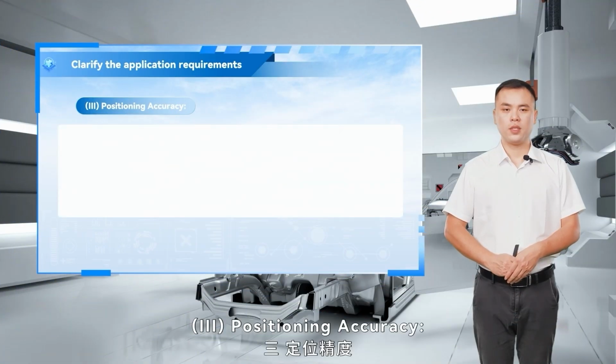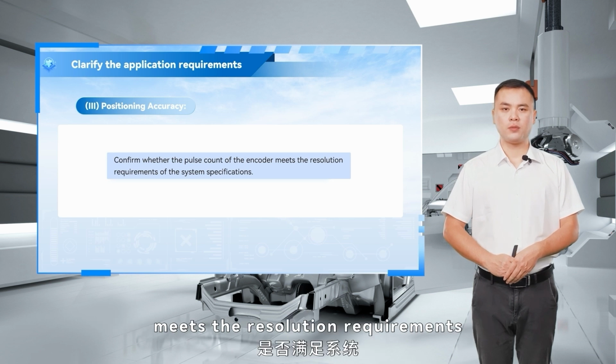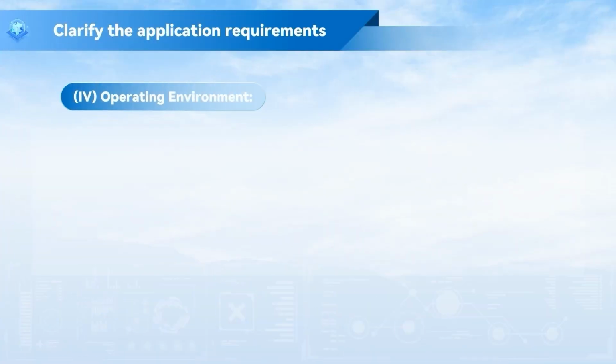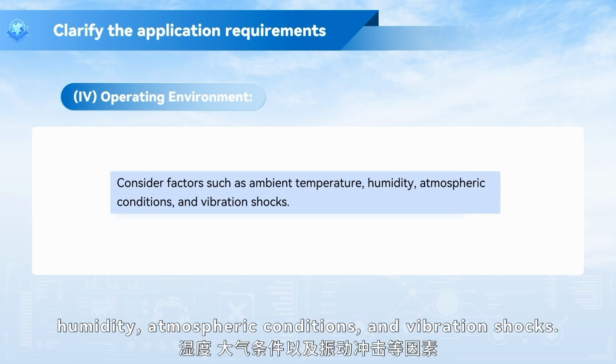3. Positioning accuracy. Confirm whether the pulse count of the encoder meets the resolution requirements of the system specifications. 4. Operating environment. Consider factors such as ambient temperature, humidity, atmospheric conditions, and vibration shocks.